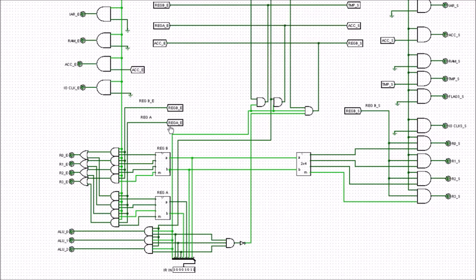So for instance, this Reg A enable goes high, or the Reg B enable goes high, or Reg B set goes high. As I mentioned before, these are just a different part of the circuit. All this is just a tunnel, and it saves us from drawing the wire from this point up to another point. So for example, this Reg B set is actually that point there, and they're the same point. We just don't want to put the wire up, it makes it cluttered.